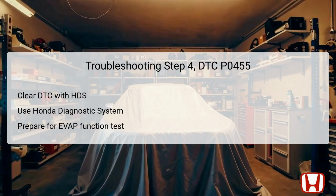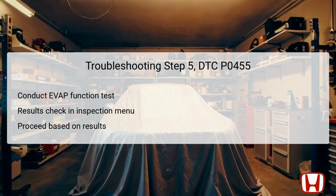Once the DTC has been cleared, it's critical to advance to the next step, the EVAP function test. This test will provide insights into the operational status of the EVAP components and help identify if any issues persist after clearing the codes. After clearing the DTC, the next step is to conduct the EVAP function test via the HDS under the inspection menu.